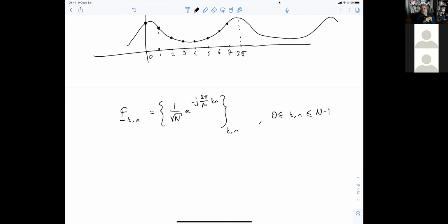Of course, there is a fast implementation. We don't really multiply the vector with this matrix, especially at large sizes. If it is 1000 by 1000, for example, there's a fast way of making an implementation, which is due to the fact that some of these terms are common in different locations of the matrix, which can be combined previously, or the data can be merged previously and then multiplied all together with one complex exponential.